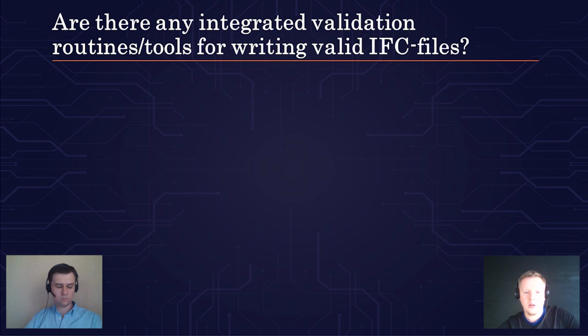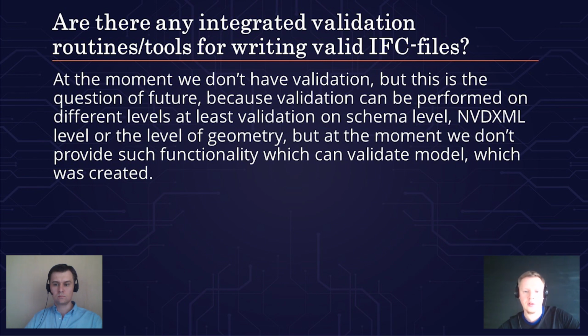Are there any integrated validation routines or tools for writing IFC files? At the moment, we don't have validation, but this is a question of the future, because validation can be performed on different levels: at least validation on the schema level, the MVD XML level, or the level of geometry.